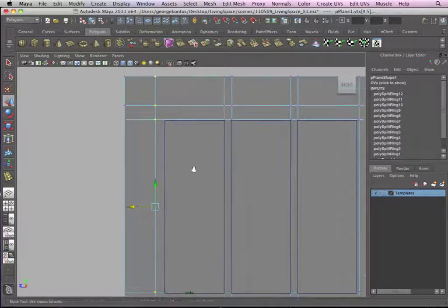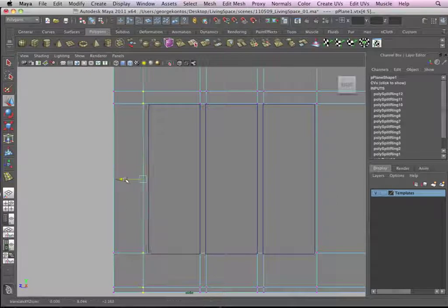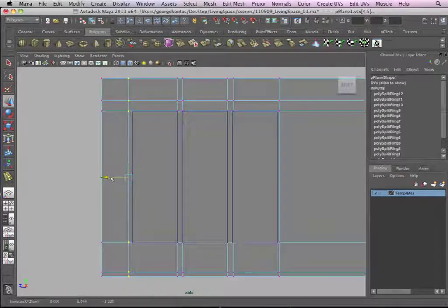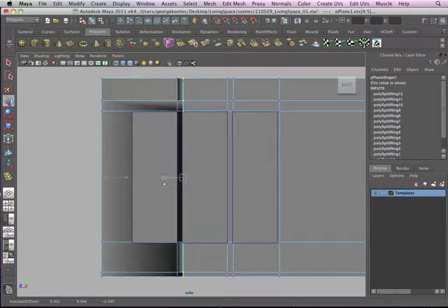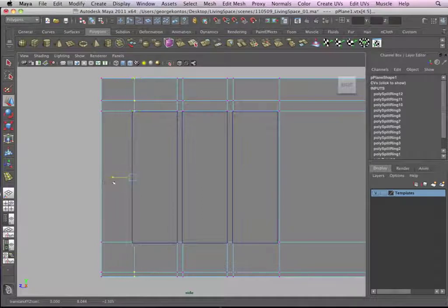One way to snap is to activate axis position. The axis of movement is going to be our Z in this case. So I'm moving on the Z. I can't move further than that point because it starts to deform the geometry. So I just need to snap these vertices on that edge. Make sure you select all the vertices and you move them on the Z, and this is yellow, so the Z is activated.